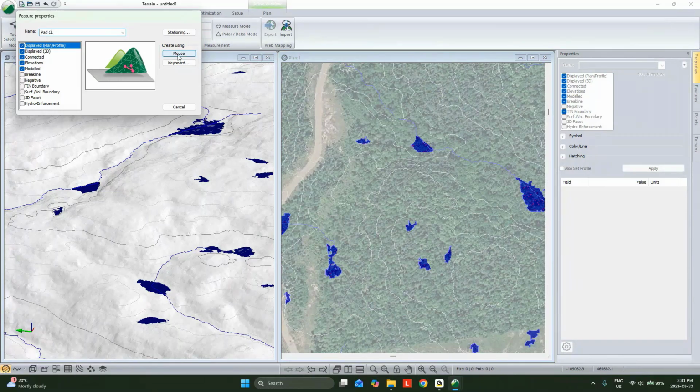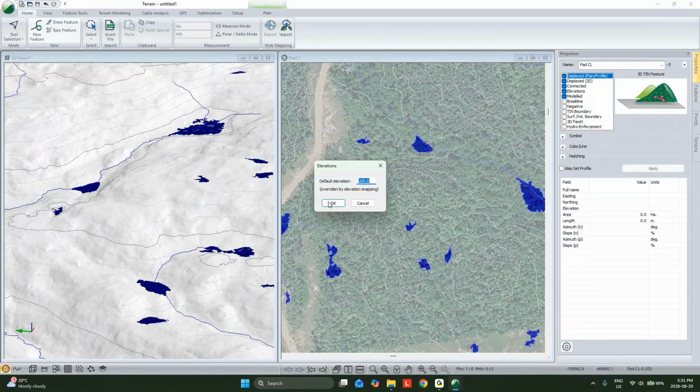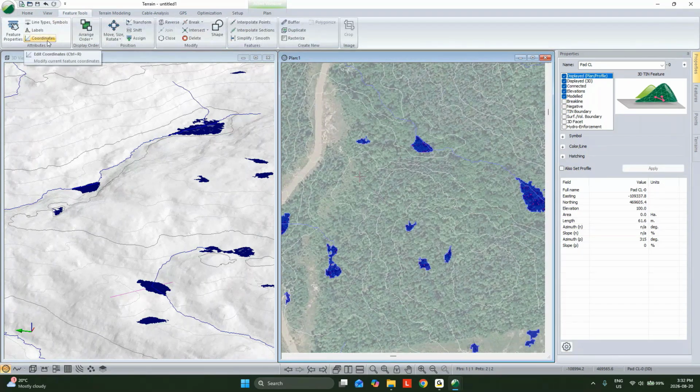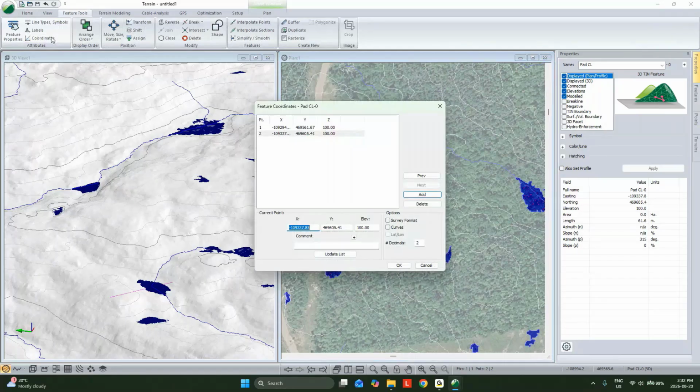Now I'm going to start by defining this feature with the mouse. We can come over here, so kind of the same area. We'll run it from there to there. Now with this, if I wanted to have that on a certain slope or a certain length, instead of doing it with my mouse, I might draw that feature in and/or use tabular inputs.